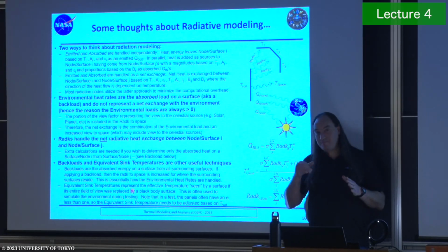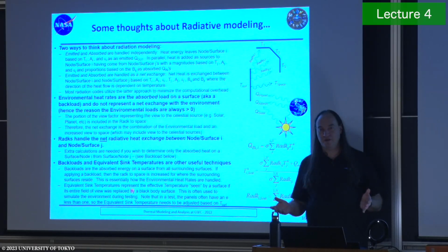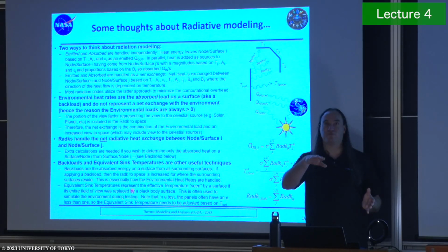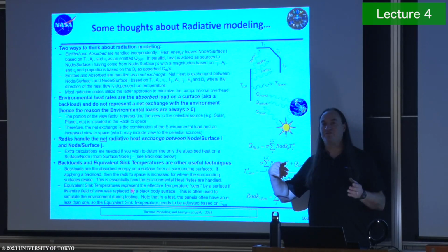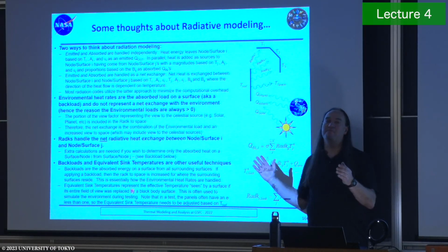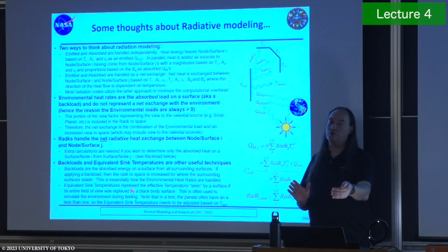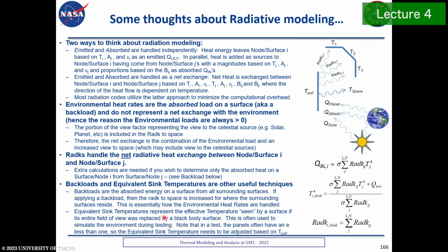For example, if I have something that's very, very cold, it's not the wavelength of energy of that, or the absorptance wavelength of that that matters. It's the absorptance or the emitting wavelength of the emitting surface that's absorbed at that wavelength at the cold surface. So when you deal with non-gray, it becomes a much bigger challenge, and you usually end up having to band it into different wavelengths of energy buckets between each of them. We basically have said IR is from 3.2 microns all the way out, and UV is 3.2 microns to the left.